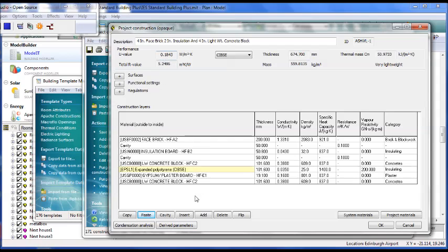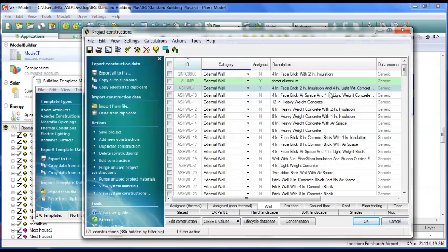And you can see the U value just dropped a fair old chunk there. At that point I can just close it and I've added it, or it's probably normally the case to adjust it to a thickness I need, and again it adjusts itself. And okay, and I've managed to insert an extra layer in without too much hassle. So we've now amended this one here. What we really should have done before we did that was to make a new layer for it so that you're not deleting the old one in the first place.